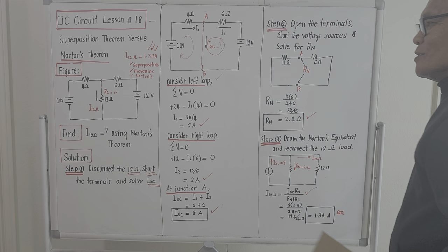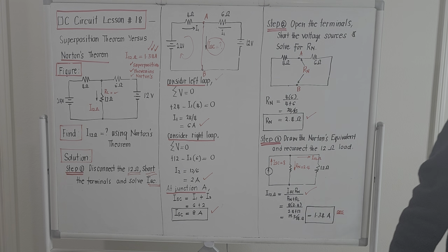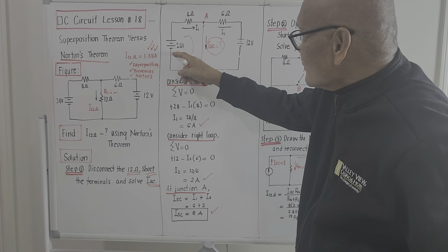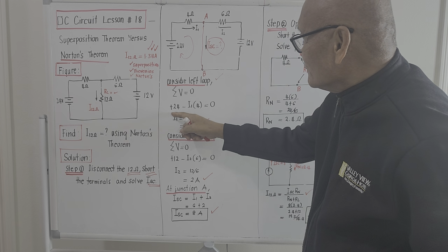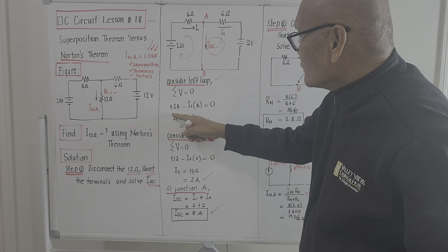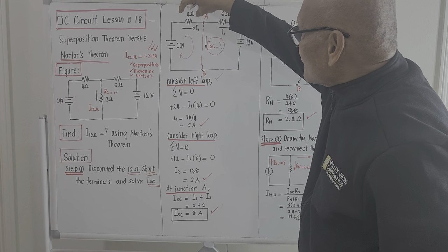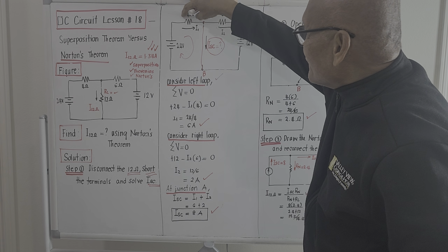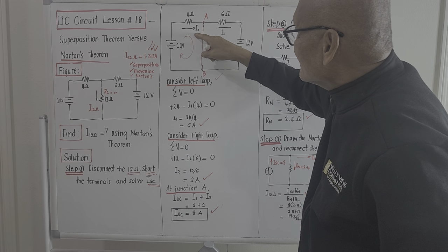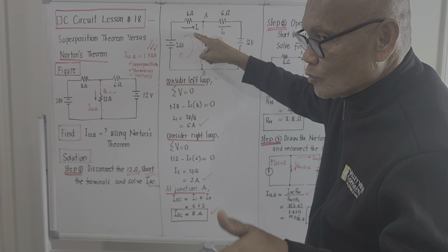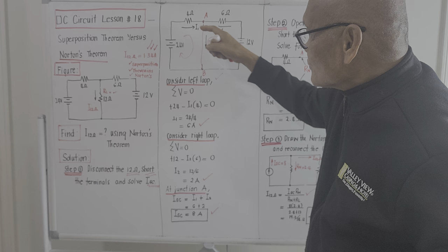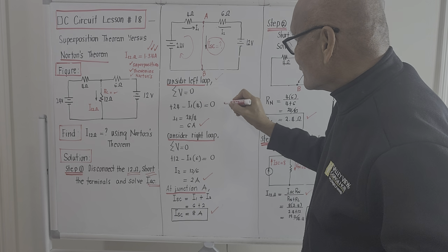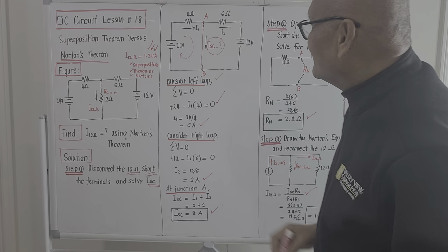Taking the summation of the voltages, this is a minus to plus, so plus 24. It's a voltage source. There is a voltage drop here, which should be the current passing I1, which we do not know for the meantime, times 4. And this will be equal to 0. Why equal to 0?